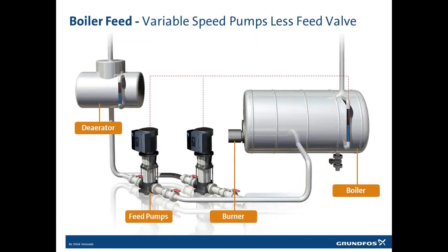Yes, we go back to this one. The frequency converter can react to 0 to 10 volts, 0 to 20 milliamps, and 4 to 20 milliamps. But since we are talking industrial installations, I will always recommend 4 to 20 milliamps because it is the most durable signal type that we know of.